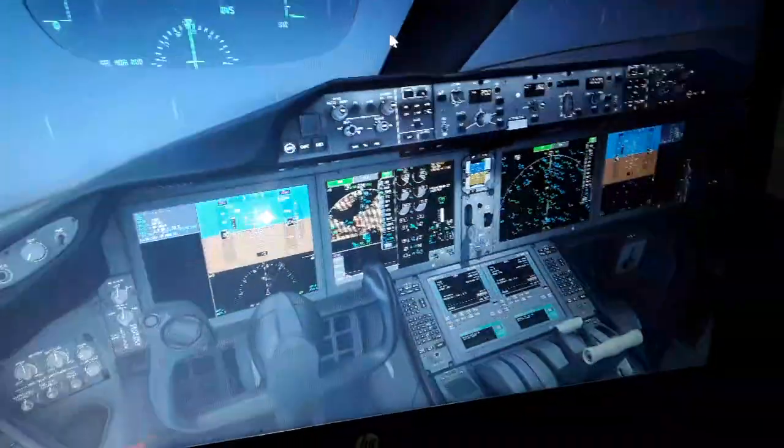So we're going to leave that now. I will talk to you about the flight controls of the aircraft. I will show you now how we're going to use also the horizontal tail trim stabilizer. We can trim the horizontal tail of the airplane when we fly, the horizontal stabilizer or the elevator. So here we have an elevator trim switch in the Boeing 787 on the control yoke, on the control wheel of the yoke.